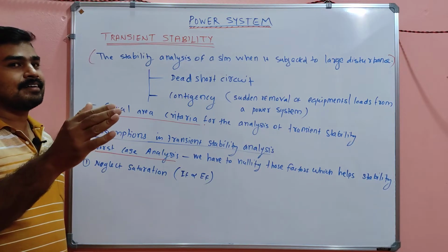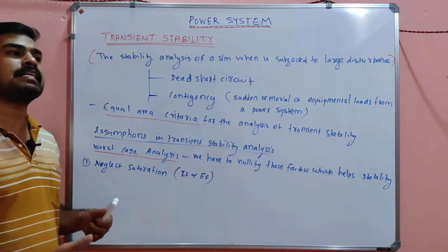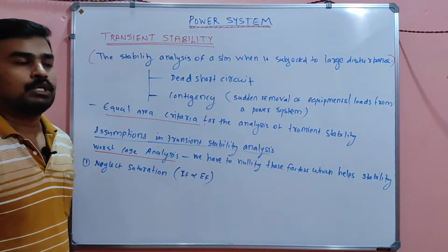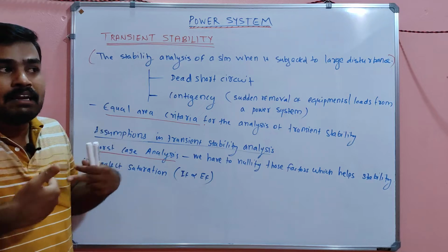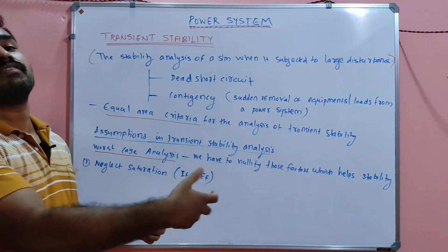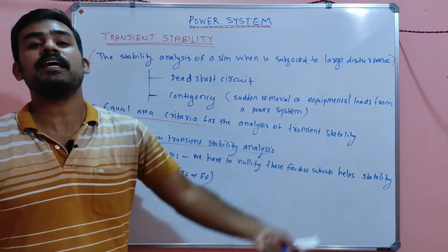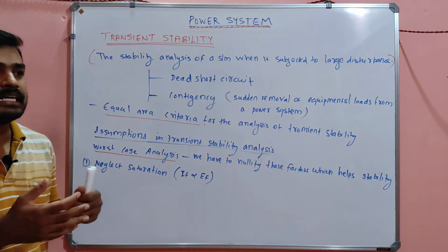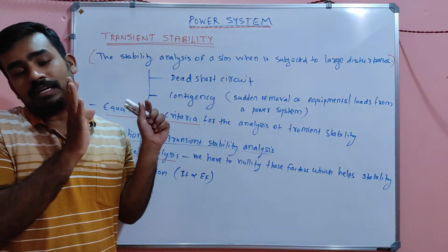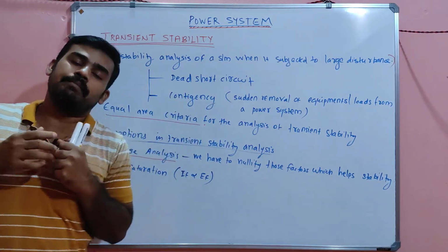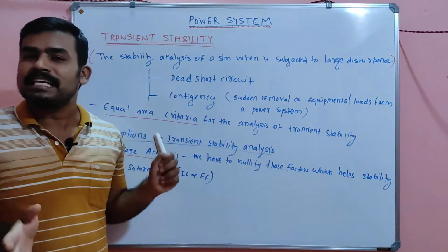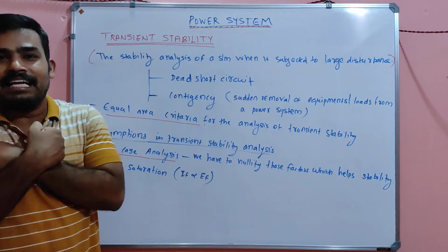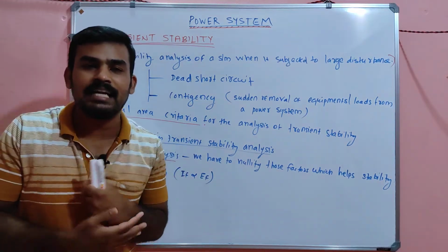If you are increasing the field current, there will be saturation, which means even if you increase the field current, there will not be any increase in the output, because it got saturated. Under saturated condition, can we get a real impact of increasing field current on the output? No, because the core got saturated. So that is actually a safe zone for us. We don't want to bother about the field current after saturation. It is a safe side for the person who analyzes the power system.